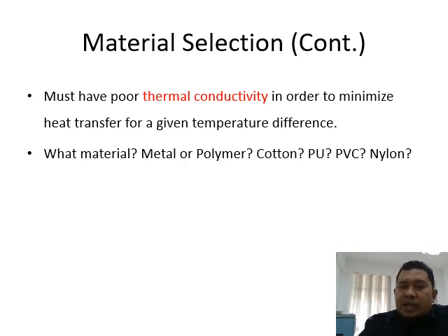So, for example, for the hydrocarbon pipe, probably you need to use glass wool. Actually, it's not just glass. The cheapest one is what they call rock wool. They're actually composites. For the thermal blanket, you have various kinds of material, depending on what temperature you want to use it at. 200 degrees, 1000 degrees, and so on.